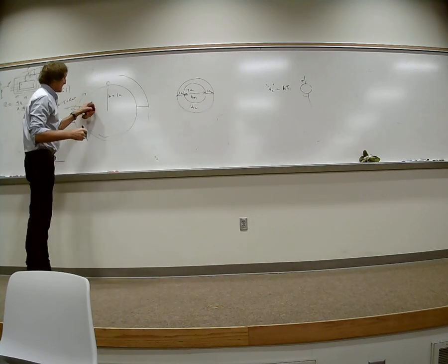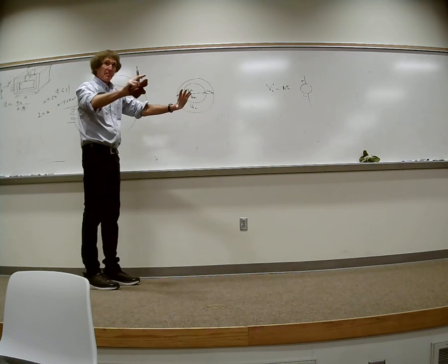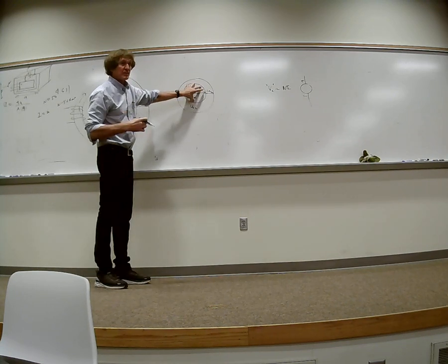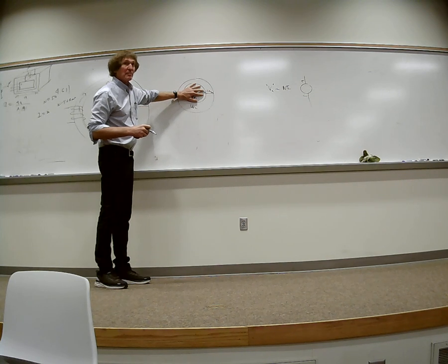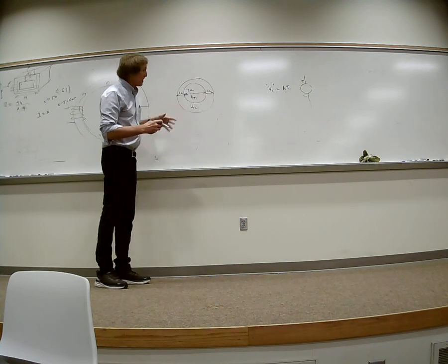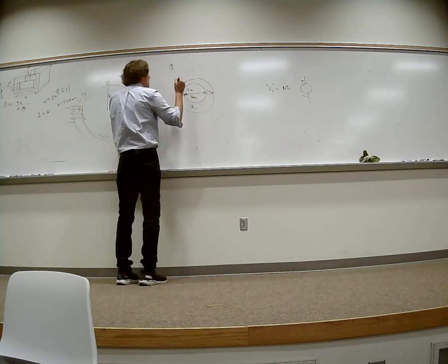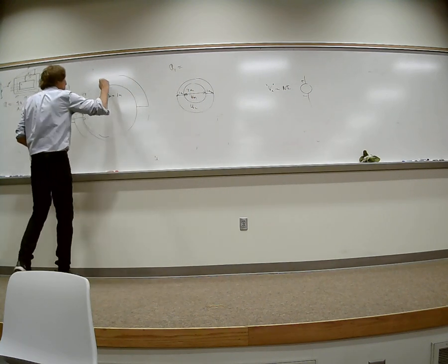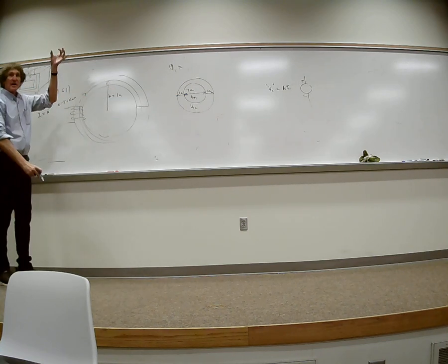Well, this here looks like 2 reluctances in parallel. If you look at this thing, just think of it as a long pipe, right? If we didn't have the outer one and just had the inner one, we would figure out the reluctance. Do you all follow me on that, class? And the reluctance of the outer one, without the inner one, is basically a hollow pipe, but they're in parallel. So what I'm going to do is get the reluctance of the inner one first. I'll call it R1, and that's going to be proportional to the length. Can you all see the length as the total circumference? If you just cut this thing and straighten it out, it's the same thing.